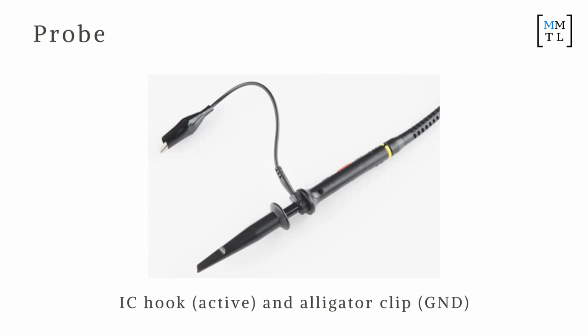Right. Okay. So let's just figure it out for this resistor here, right? Okay. So if I want to figure out this resistor here, I'm going to change this. I know that it's going to spike to 5 volts. So I'm going to change the resolution up to 2 volts per box, right? And so we're going to expect to see a line, for example, right? I can also do 1 volt. If it's 1 volt, then I expect to see a line here. Okay. And then another thing is time. Time is probably less important for this one because it's just going to appear or not appear.